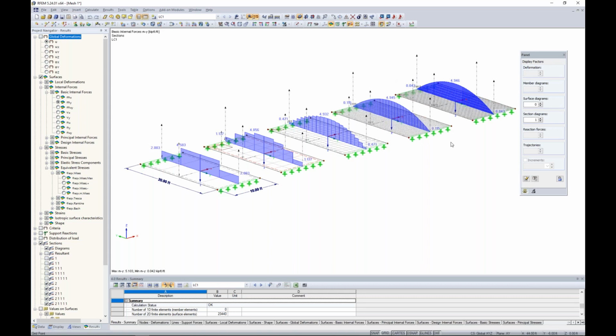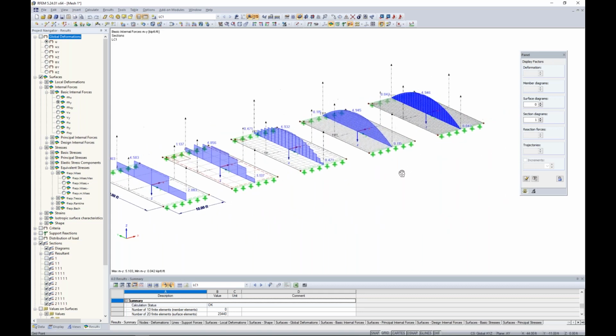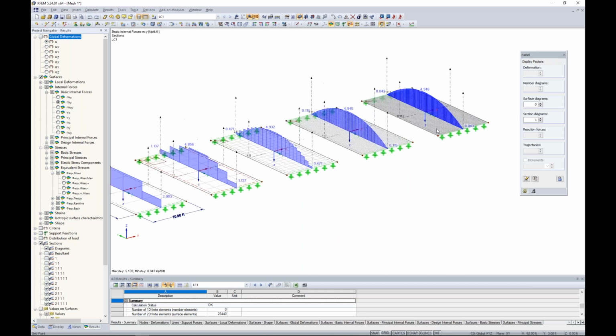4.946. So at some point, our cost to benefit ratio, so to speak, where we're continually refining this FE mesh, is really not drastically influencing our results. For example, these two elements here: the one on the left has about one third the FE mesh that the one on the right does, yet our results are only changing by 0.001. So it's this happy medium, finding the right balance of when we are able to refine our FE mesh to gain accurate results, but not so much that our calculation time is increasing significantly because we've added all these additional elements.